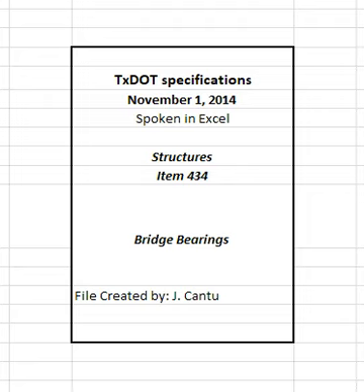3.2.2.2 Documentation. Furnish copies of certified mill test reports for the steel top, sole plate, stainless steel, PTFE faced steel plate, and any required steel special components. Provide a manufacturer's certification that the PTFE material meets the requirements of this item. Furnish certified laboratory test results on the elastomer properties of each batch or lot of compound for laminated elastomeric bearing pads.